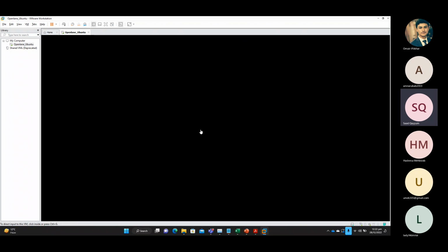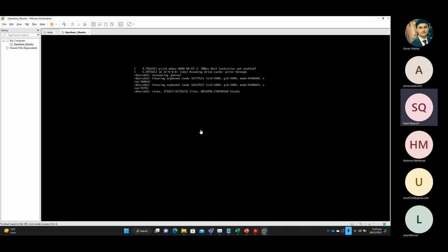What we're doing is a hierarchical design. So this is meant to be an interface for the symbol. And if you want to simulate inverters, you would create a symbol first, then instantiate that symbol in a bigger schematic, like the way you do it in, let's say, Verilog, you create a module and then create an instance. So that's what we're doing.